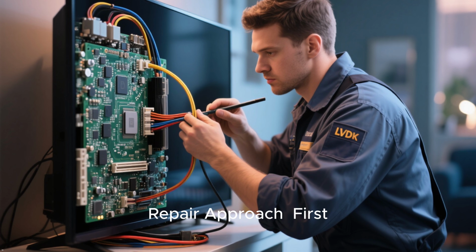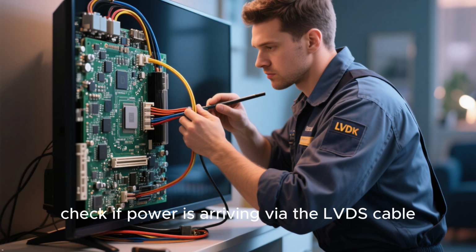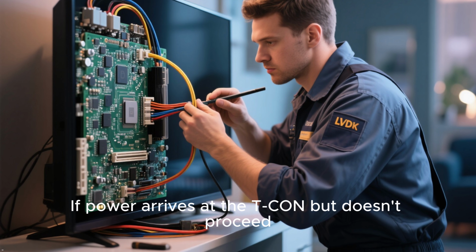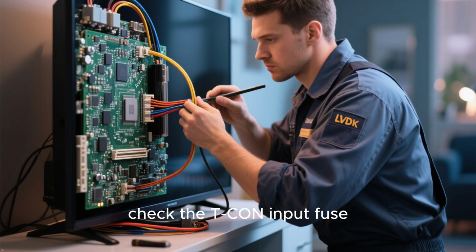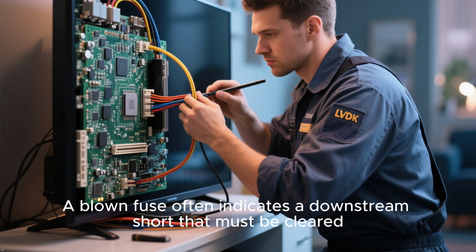Repair approach. First, check if power is arriving via the LVDS cable. If not, trace back to the mainboard's panel supply section. If power arrives at the T-con but doesn't proceed, check the T-con input fuse. A blown fuse often indicates a downstream short that must be cleared.